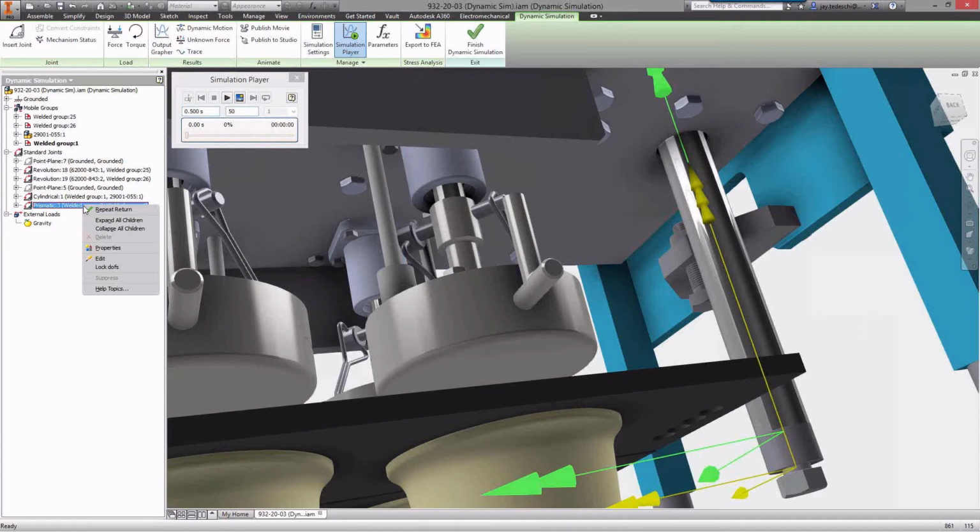When you assign an assembly constraint, you pick entity 1, you pick entity 2. By virtue of where you select the component to apply the constraint, and I'm not talking about the global origin, it assigns an origin. As you can see, those two origins are different, and they need to be a single unified reference frame for our results to be valid.